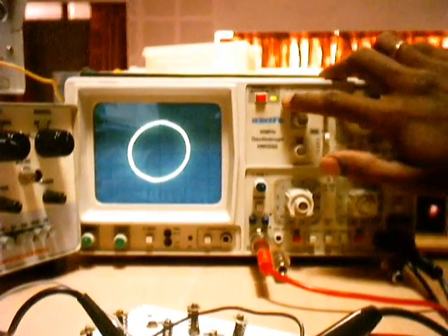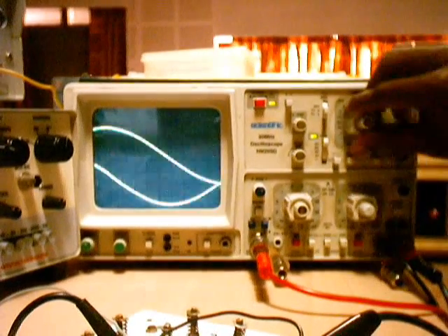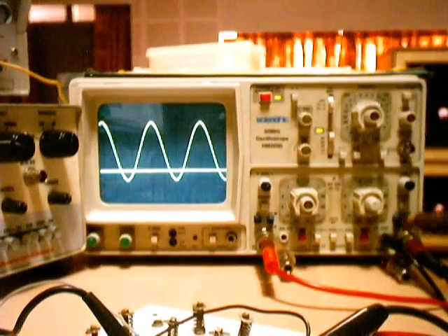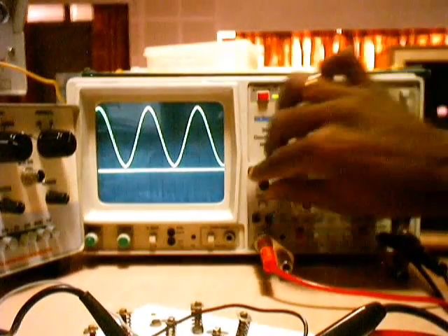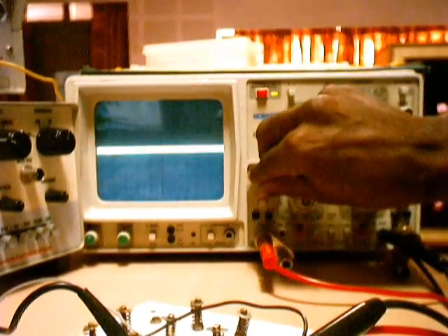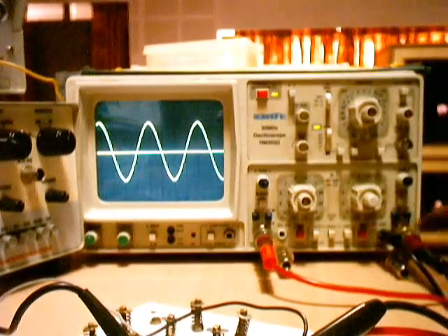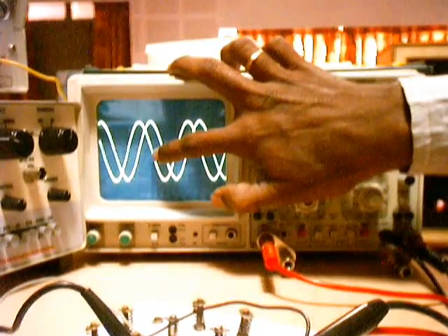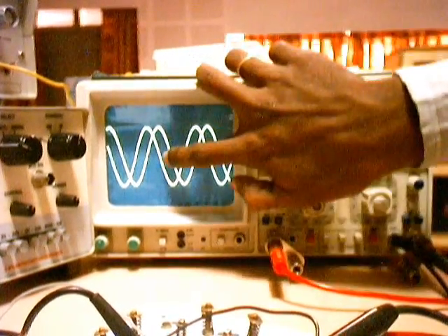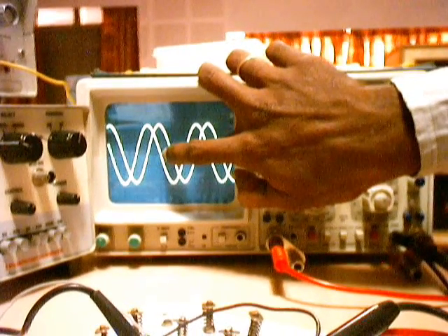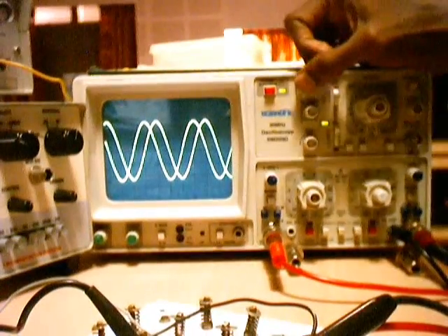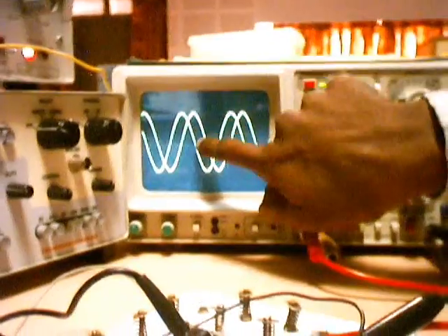You can clearly make out whether they are 90 degrees out of phase or not by releasing the XY mode and pressing both. Can you make out this? Let me coincide both input and output over here and release both of them. When the input or the output is at 0, you can see the other one is at 90 degrees. This is the zero crossing of one of the waveforms, and the corresponding other waveform is at 90 degrees, which ensures that they are 90 degrees apart. We cannot so easily measure the phase shift otherwise.